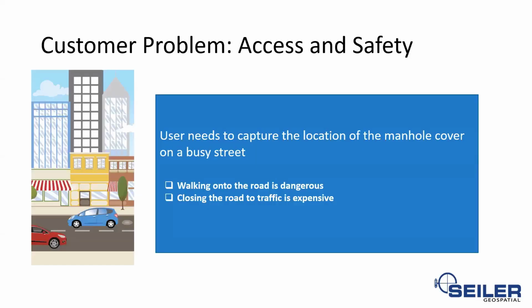So what's the problem with this? The problem is you may not always be able to get good GPS or GNSS within the areas that you're at. And then also too, for safety of workers, you do not want to send your crews out into the middle of the street to try and GPS a manhole lid or a water valve or other assets that may be in the median. It just may be too unsafe to get involved in a downtown setting or a busy highway. So enclosing the road can be quite expensive and time consuming, and or has to be done at night, and nighttime construction is not necessarily the safest either as far as trying to block off a road and do mapping or surveying.